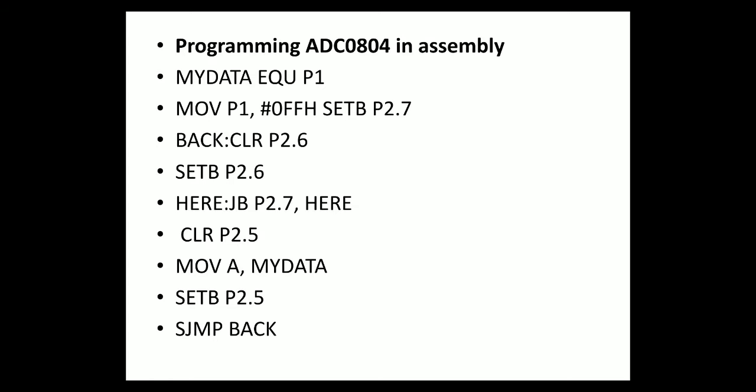Is to check the status of your INTR. So how do I check that status? JB P2.7 here. So you are monitoring whether it is becoming 0 or not. It's already 1. Okay, you are verifying whether it will become 0. And when does it become 0? When the data conversion is completed.